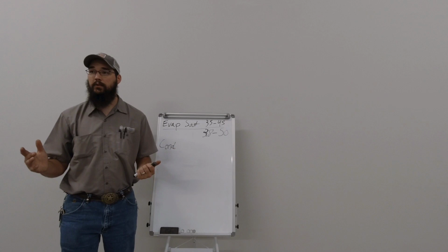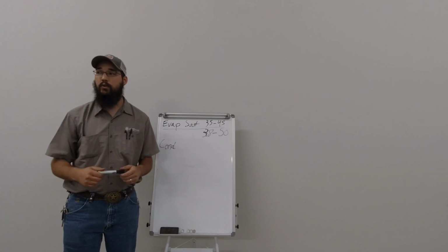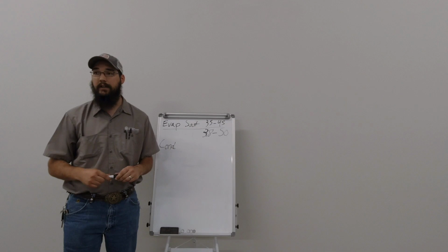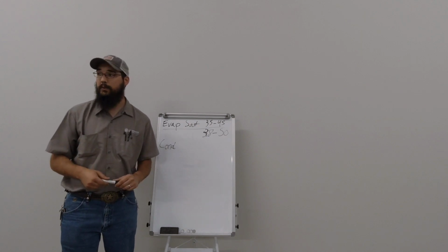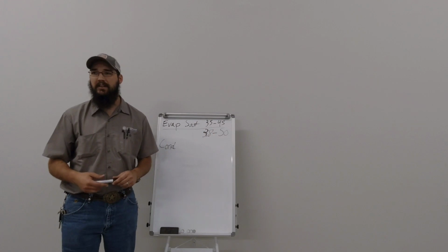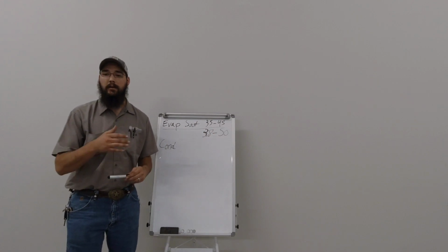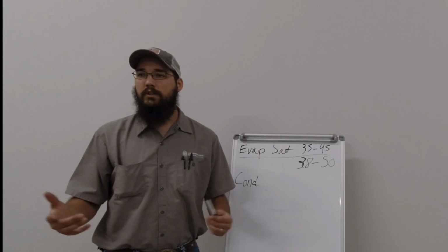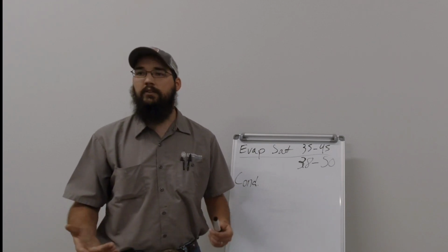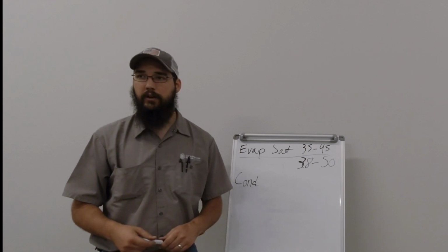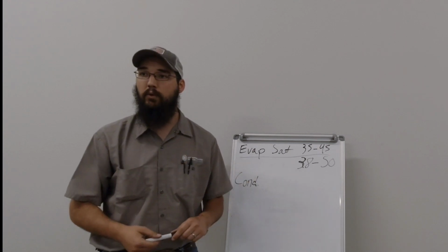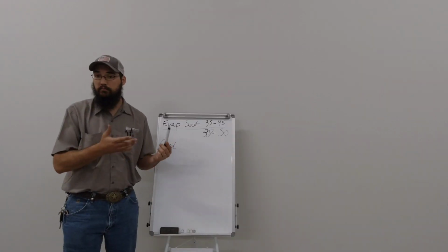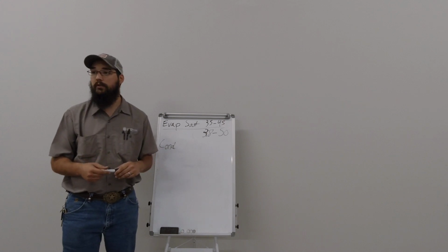The whole point. That's why many of your microchannel coils tend to be very sensitive. Lennox catches absolute hell out of their microchannels because the way they put them in such tight tolerances when they built them, especially their earlier series. They've gotten a little bit better about it now, but you have to wash them multiple times a year for them to even have a chance of running. That's something Lennox learned the very hard way when they were really trying to push a lot of that forward. They came up with some very well-working systems, but they ran into problems when doing it.